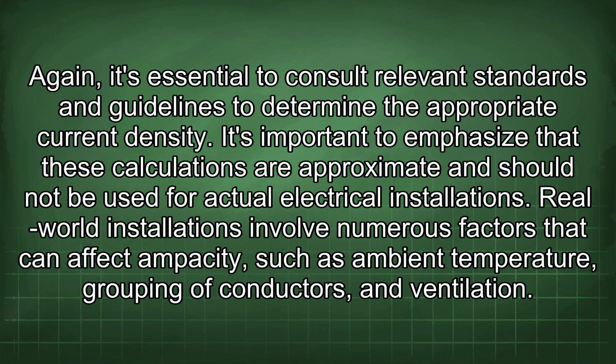Again, it's essential to consult relevant standards and guidelines to determine the appropriate current density. It's important to emphasize that these calculations are approximate and should not be used for actual electrical installations. Real-world installations involve numerous factors that can affect ampacity, such as ambient temperature, grouping of conductors, and ventilation.